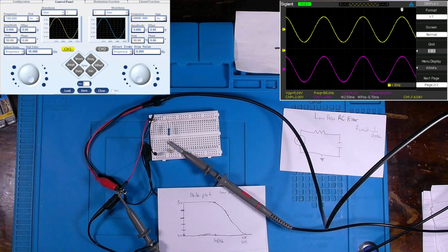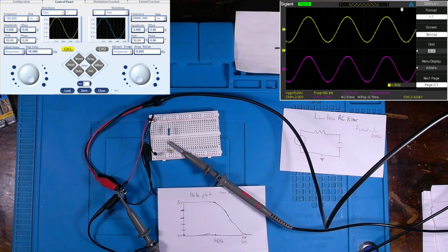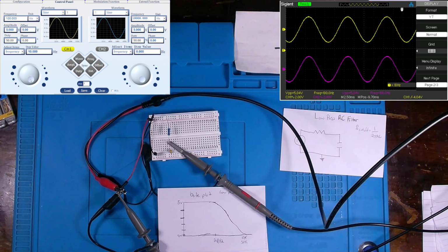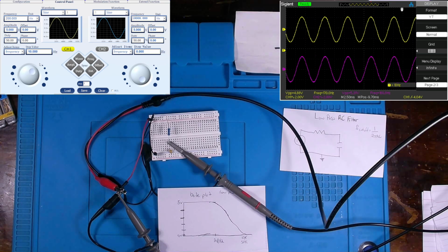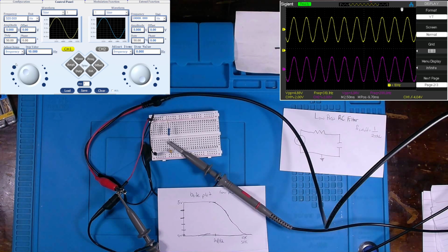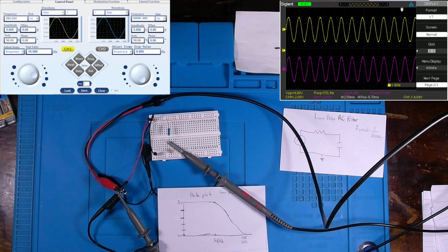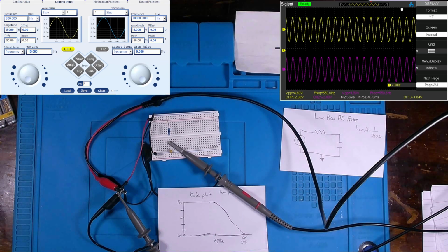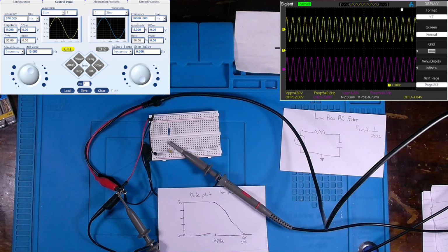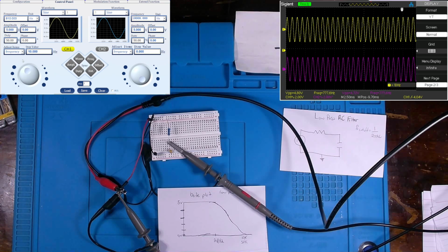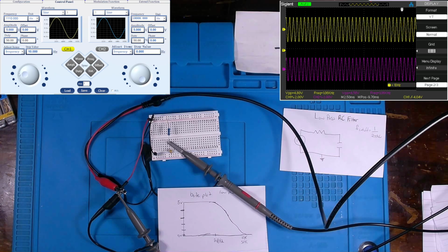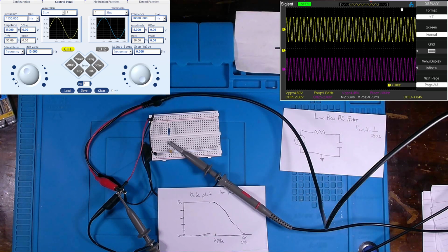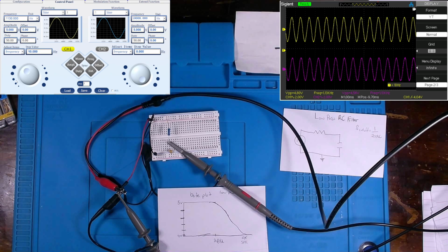That's probably just due to the probe itself, or maybe a bit of compensation, something occurring there with my probe. But anyways, as we increase the frequency, you see how I have my step set to 10. We'll start to increase this, okay? And we can see that that amplitude is, man, it's staying very similar, okay? As we increase frequency, our amplitude is unchanged. Let's get up to about 1130. We see that there. I'll span out a bit.